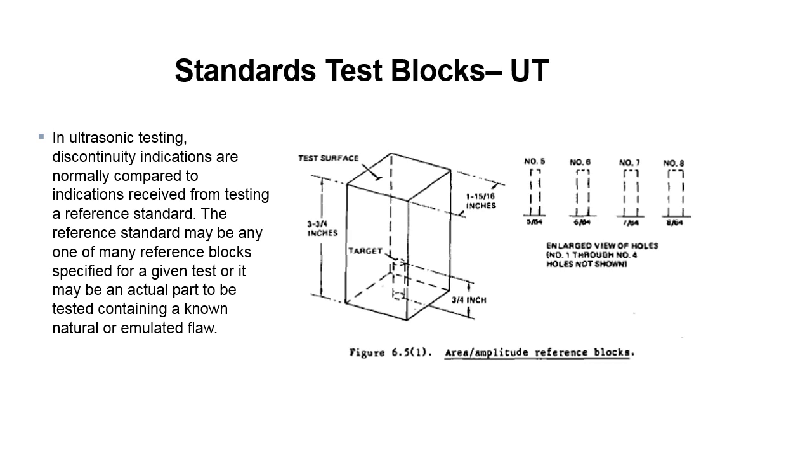flaw or hole or defect, manufactured defect or notch, whatever he's trying to find. He's got to switch over to that on that material. So once you get a machine calibrated for a certain type of carbon steel, you can't use it on stainless steel or a nickel alloy or aluminum or titanium. It's got to be specific. So you have to have specific standards and test blocks for whatever material you're testing.